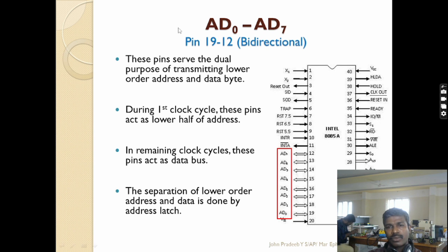Next, regarding the address and data bus, we have AD7 to AD0. These pins are used for dual purpose, address as well as data. They are pins 12 to 19, where the address and data are present. Here ALE is used for address latch enable.